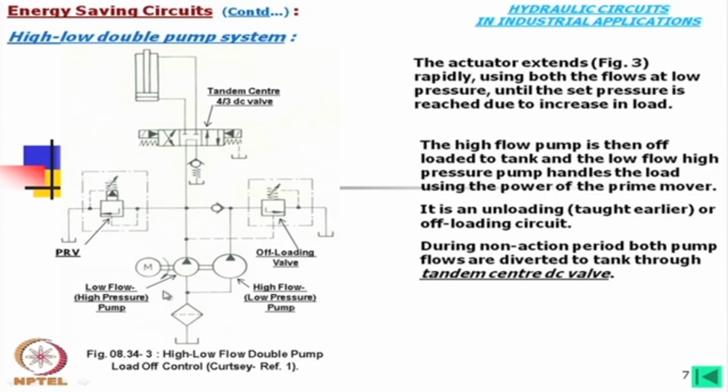Then this means that this pump will operate with 10 megapascals, and then this pump will operate at low pressure and oil will go back to the tank. But still, if you think of 10 megapascal of this flow, almost the full power of motor will be used. In that case, say power is being wasted.